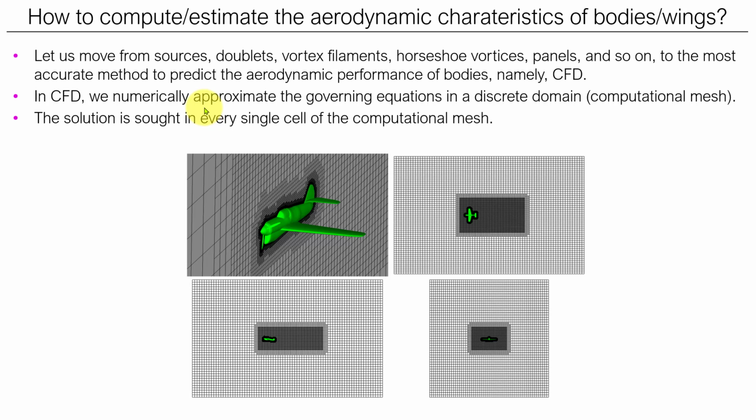But basically, the idea in CFD is that you need to subdivide your domain in many control volumes, you see here. Previously we haven't done this. Okay, and if we have done something like this at the surface level, we don't know what is going on in the domain. So here you need to subdivide this in many small pieces, control volumes, and in each one you are going to find the solution. So it's clear that the more elements that you add, the more accurate, or we hope the more accurate the solution will be. Not necessarily.